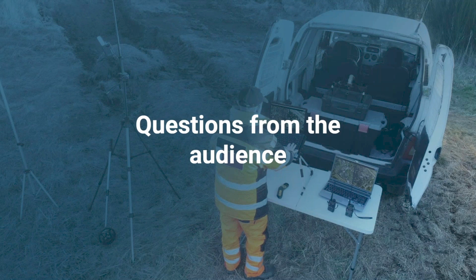Now, how accurate is React itself? Well, it's pretty accurate. It's going to be a couple inches. Sometimes it's going to be an inch, sometimes it's going to be half an inch error, sometimes it's going to be 3 or 4 inches error. It really depends on what you're looking at and the camera and the drone that you're using, as well as what the overlap is. With Pix4Dreact, you can get away with less overlap than you could with Pix4D Mapper. You can fly 60% front, 60% side overlap, and it will work. But if you fly with that 75% front overlap, 70% side overlap, you're going to get a little bit prettier of a map.